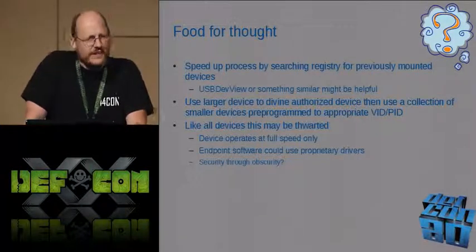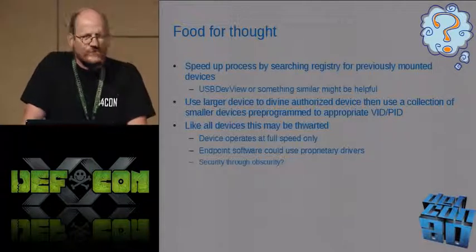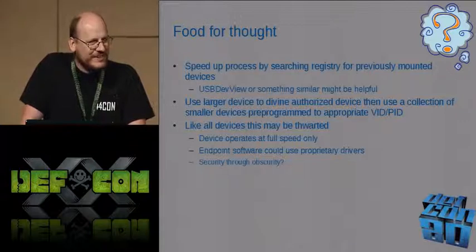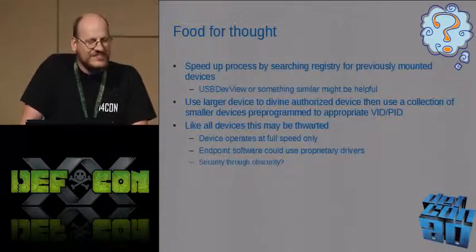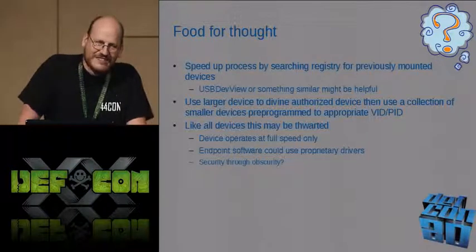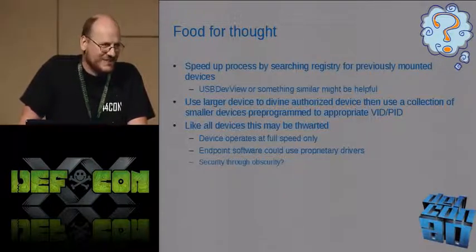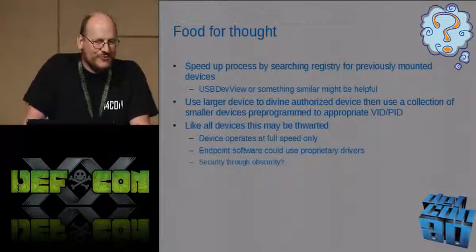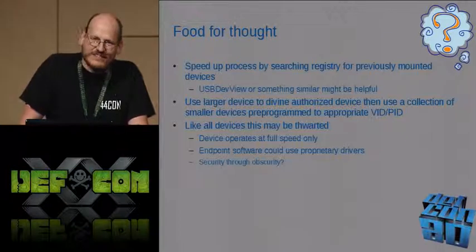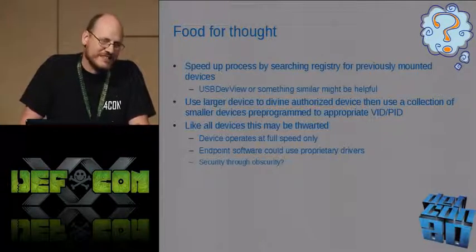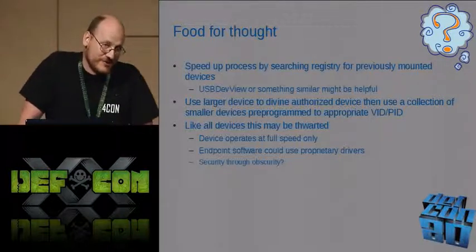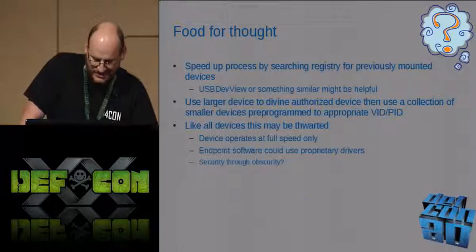One other thing, who remembers what's the maximum packet size for a full-speed USB endpoint? 64 bytes. What is the default block size? 512. So what happens is it has to fragment and unfragment all those blocks. So that does give you a little bit of a performance penalty, unfortunately. But I don't know how you could do anything better other than find something that supports full speed.